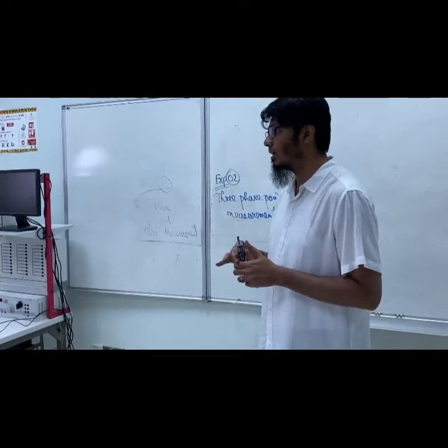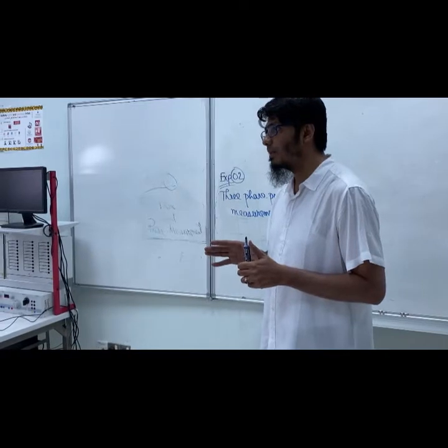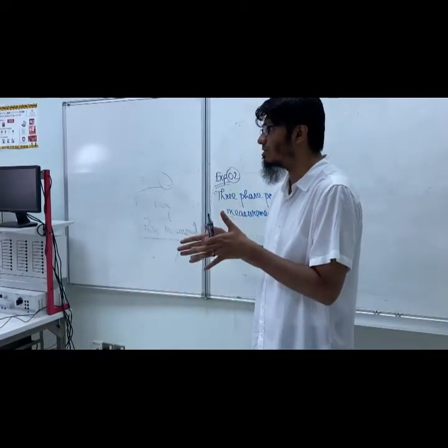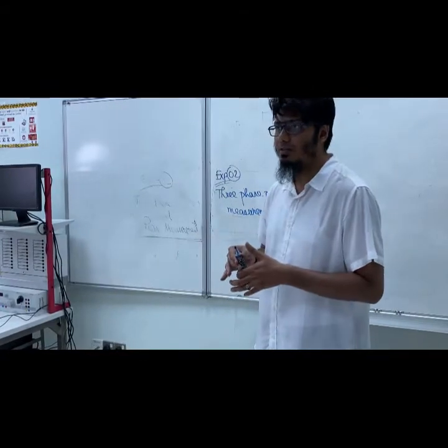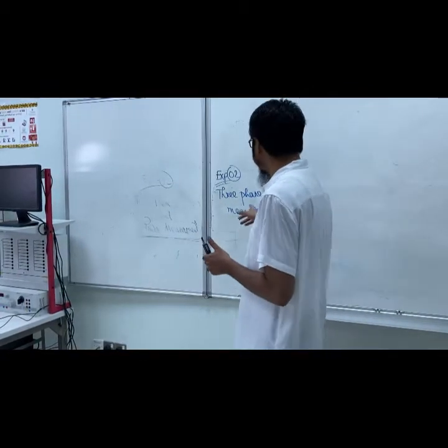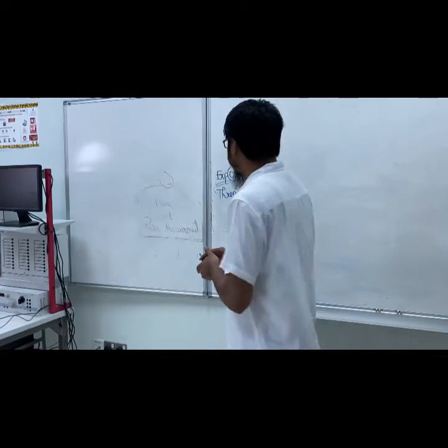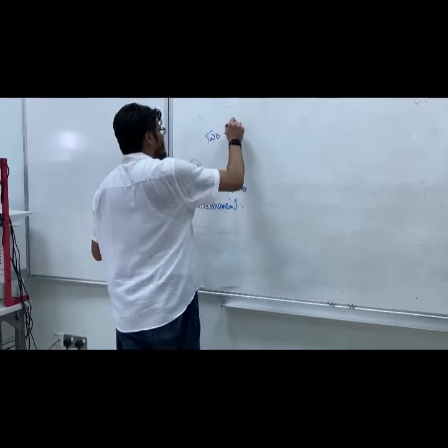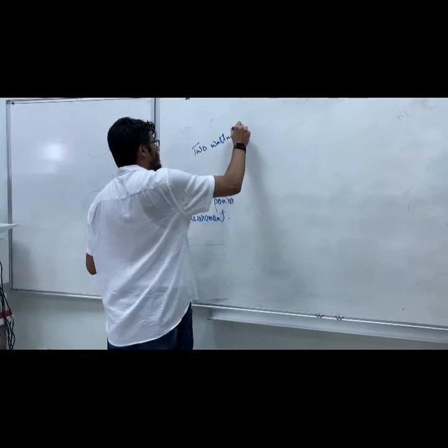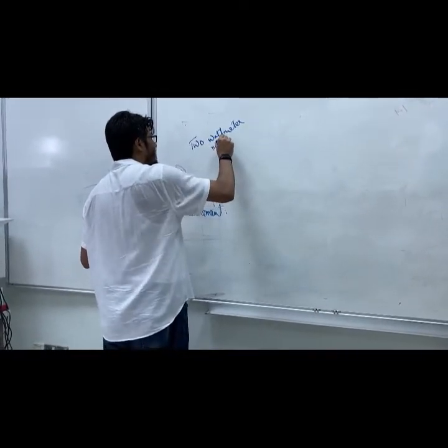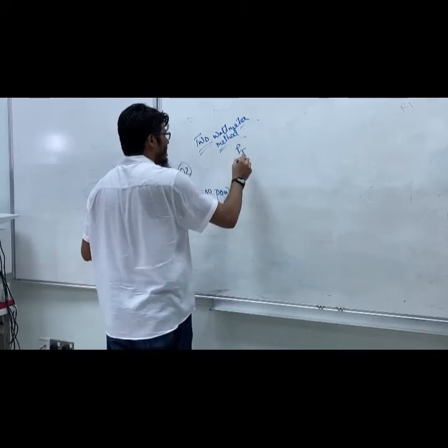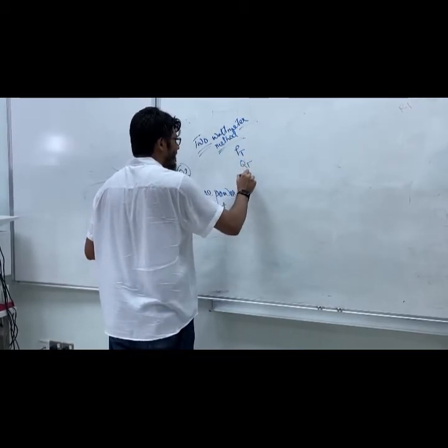Now today we're going to deal with a three-phase power measurement circuit, and this part was completely covered in our lecture. Can you remember the 2 wattmeter method? I think the second half of the lecture was regarding the power measurement in three-phase circuit, right? We measured the power using the 2 wattmeter method. From this method we can get the total power PT and QT and the angle theta.